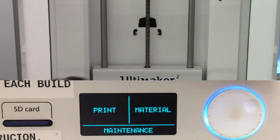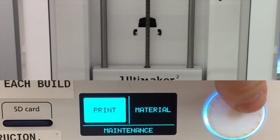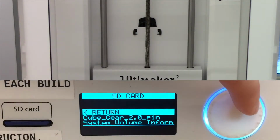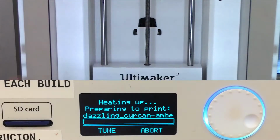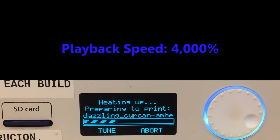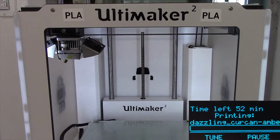Next, we'll go ahead and navigate to highlight the word print, press the button, and navigate to the file that you have loaded on the SD card. After depressing the button, you'll see that the nozzle is heating up, and this is typically one of the most rate limiting steps of the process. Here it's played back at 4000%.